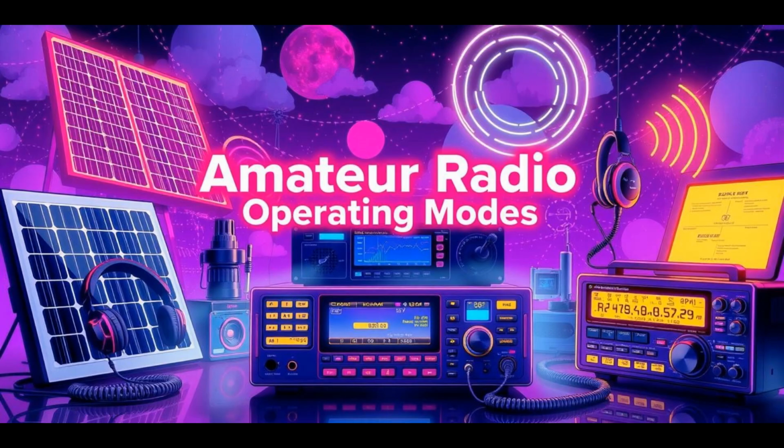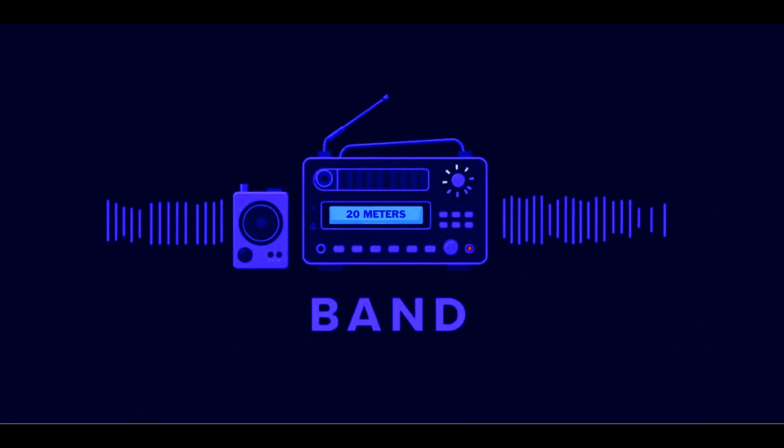In order to put this in perspective, I need to go over some important concepts: band, frequency, and mode. A band is a segment of frequencies grouped together because they behave similarly in terms of signal propagation and are designated for particular uses. A band in amateur radio is simply a defined slice of the radio spectrum reserved for amateur radio use. Each amateur radio band is identified by its approximate wavelength in meters or frequency range in megahertz. Each band has unique properties that determine how far signals travel by ground wave, sky wave, or line of sight. It also determines when frequencies work best. This also impacts the type of antennas used and how they perform.